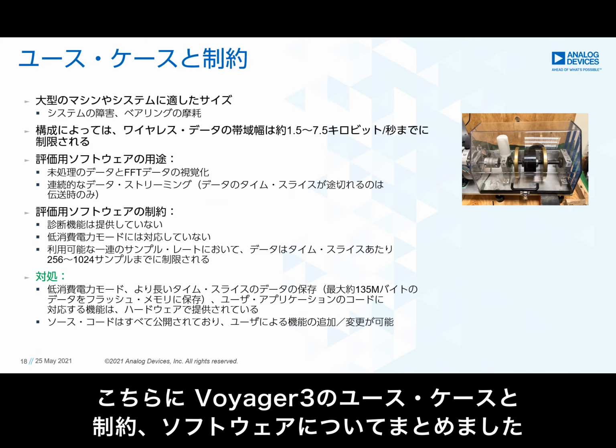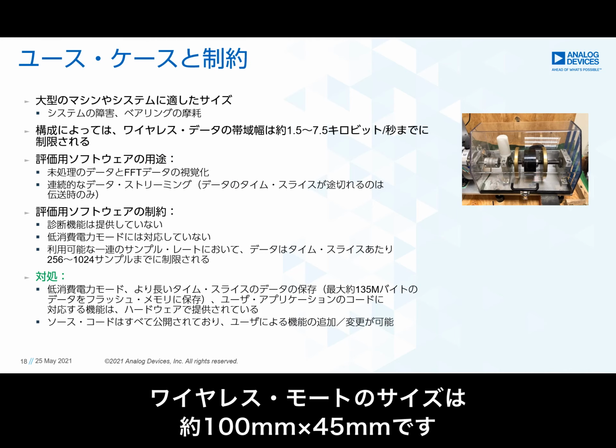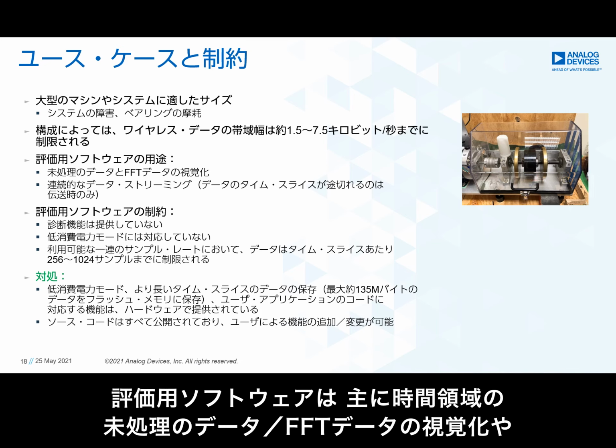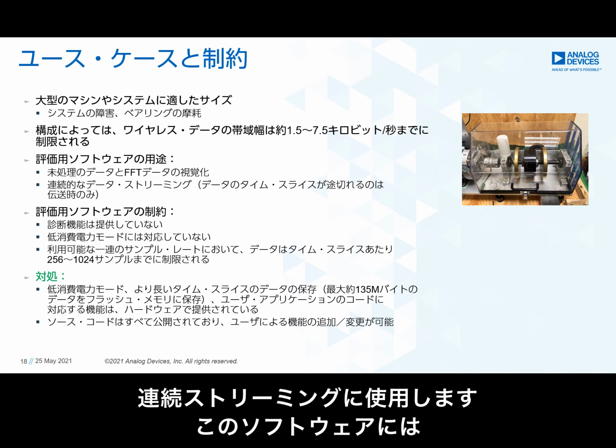Moving on now, the slide presents some details on the use cases and limitations of using this platform and the existing software setup. Firstly, the wireless mote measures approximately 100mm by 45mm, so it's best suited to larger machines and systems. The focus of the evaluation software that we provide is visualization of raw time domain and FFT data with continuous streaming.